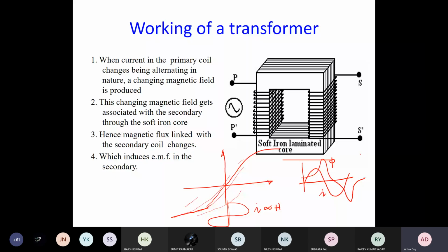But if you get a BH curve which is very small like this, I mean your area is very small, and if you use a sinusoidal H, your field intensity, you will get a flux density which is approximately sinusoidal. Then there won't be much harmonic content in it. If harmonics are less, then your losses will also be less. That's why we go for the CRGO based core, so that your hysteresis loss is less.